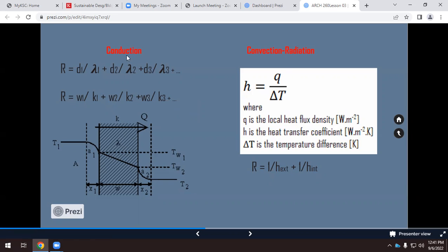So it's not difficult. It's just a formula. We need to know what thermal resistance is, and then we have to add everything up. If they are asking, or we have to give an R value, that's it. If we have to give a U value, then we have to divide 1 divided by R, and then we have the thermal transmittance, the U value. So it depends. In different codes or different regulations, we have to use R or we have to use U. But if you have calculated R, calculating U is a piece of cake.